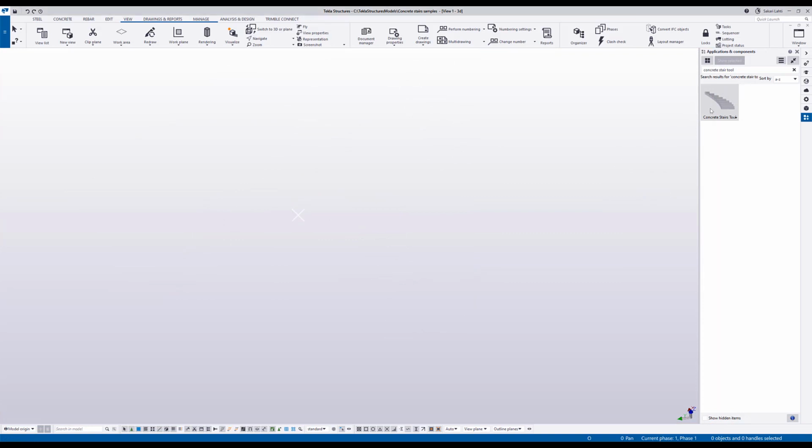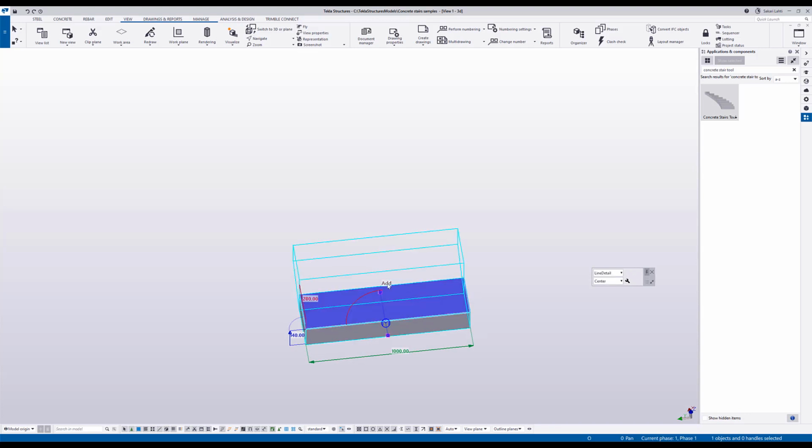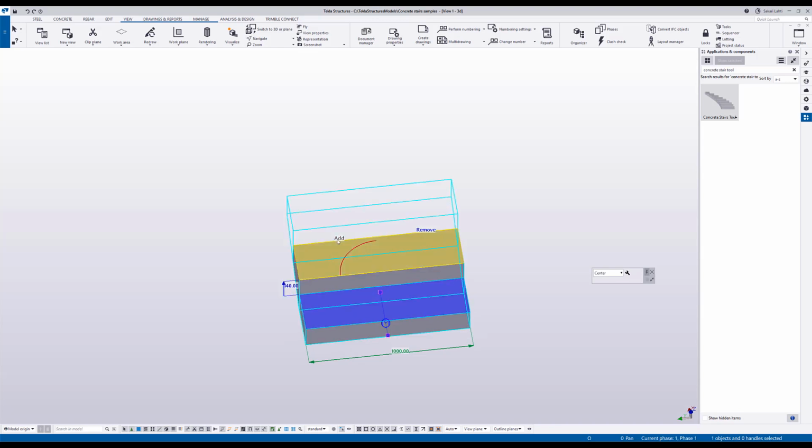One more method of creating the stairs is the last option in the contextual toolbar called Advanced Stairs. There you basically first create one step. Then you select that component and individual step inside of it. There you will have controls over the height and the side lengths of the steps. And you can add more steps by pressing the Add button.